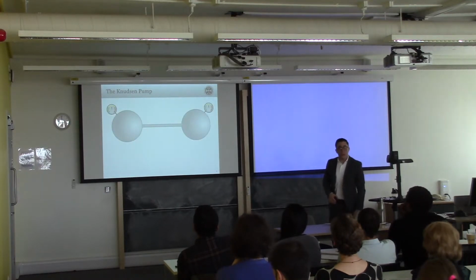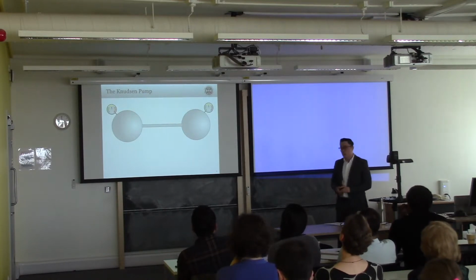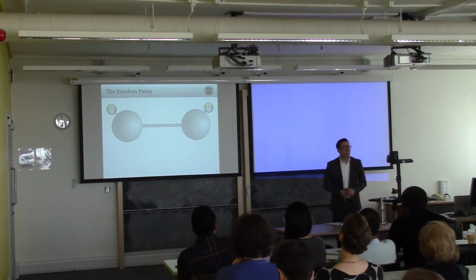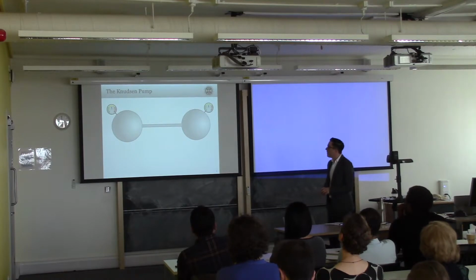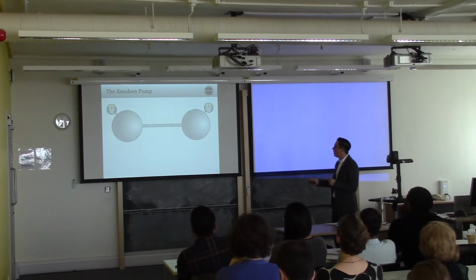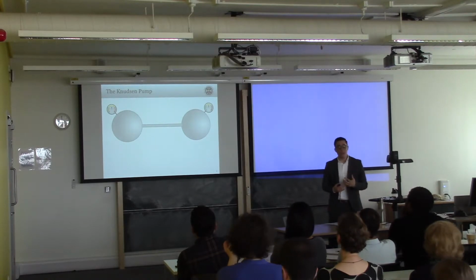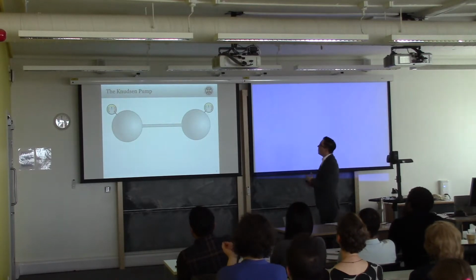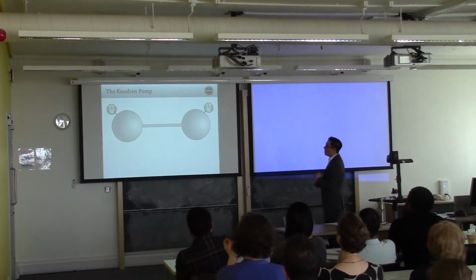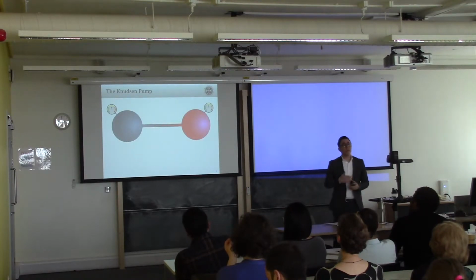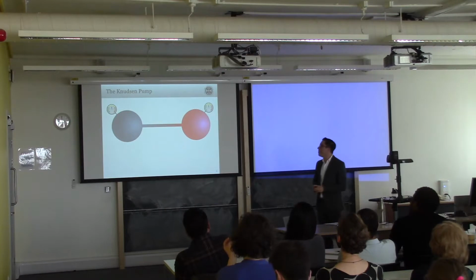So I'd like to show you, I have two stories to tell, two applications to show you with regards to applying these multi-scale methods. So this is a Knudsen pump. It basically contains a capillary, and this Knudsen pump produces a flow without any moving parts. In this particular configuration, I've added two reservoirs because, as I'll show in a minute, there's an experiment linked to this. So the flow is generated not by a pressure gradient, but by a temperature gradient.